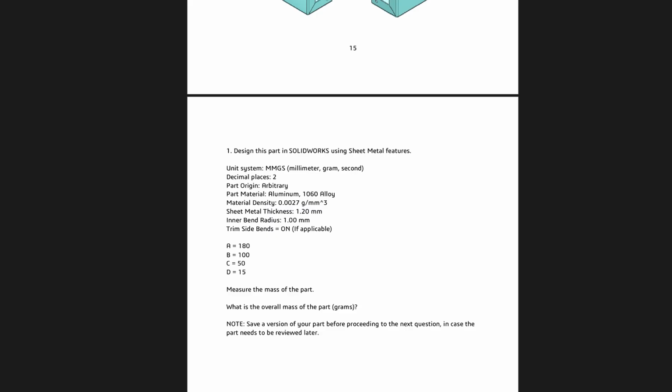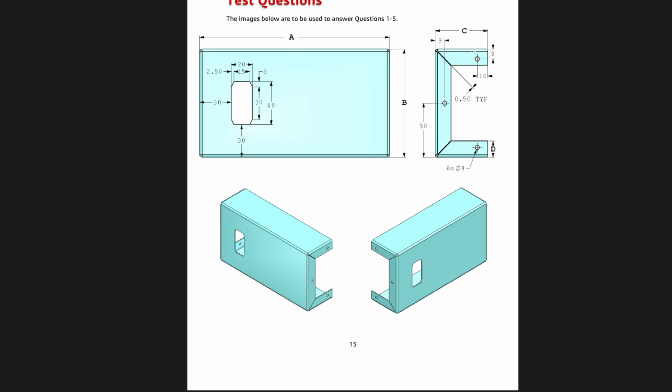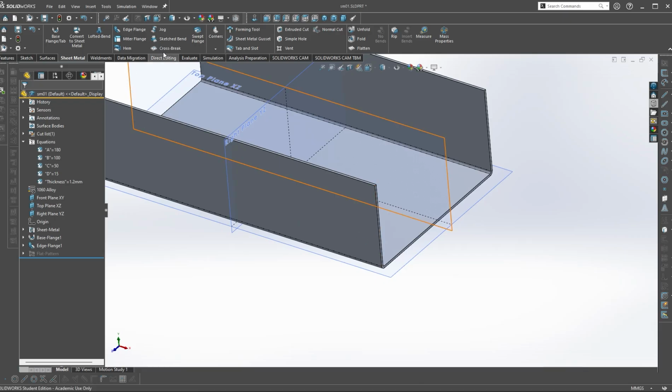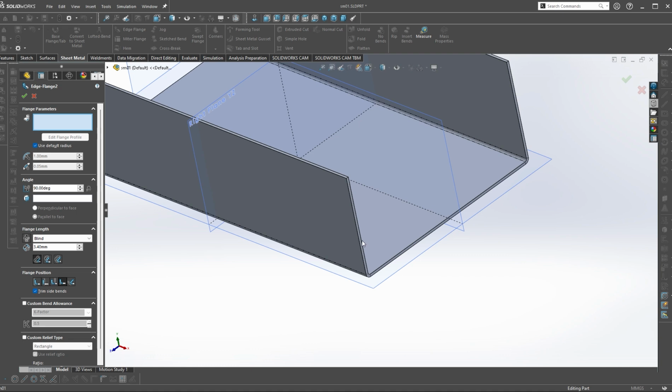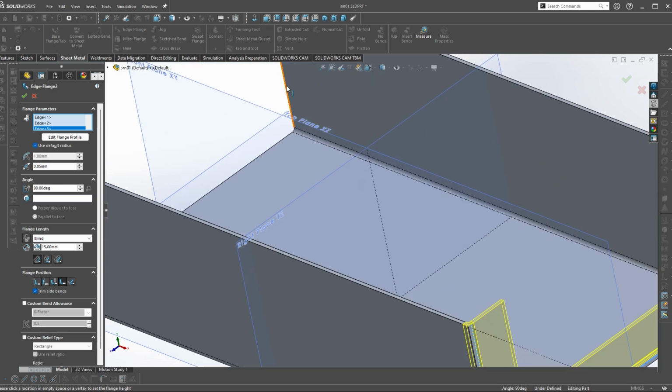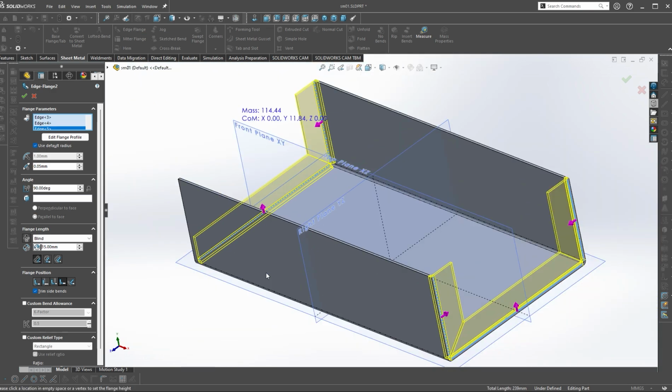Now that we've got the sidewalls put in, let's kick up these almost like a tab on the end here, and the D is going to be the depth for these. So I'll start up a flange again, and we're going to go here. Again, we set something arbitrary for the time being, and then we just override that with our global variable setting of D. Now I can come back in, do this, and we can actually do these edges as well.